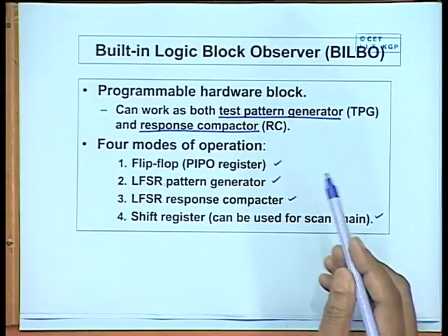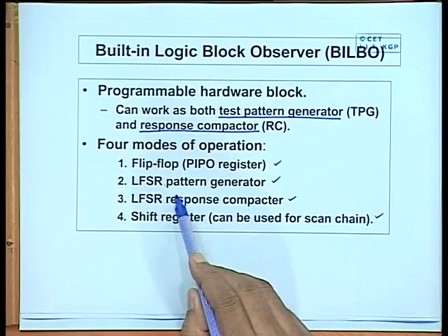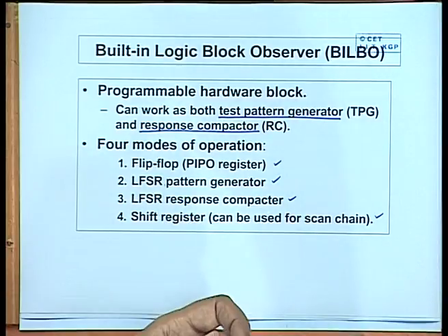Okay. Now, just one thing I would like to mention before I proceed further is that we are talking about an LFSR based, on chip pattern generator, but usually the patterns generated are not exactly the type generated by a test generator program, which we had discussed earlier.